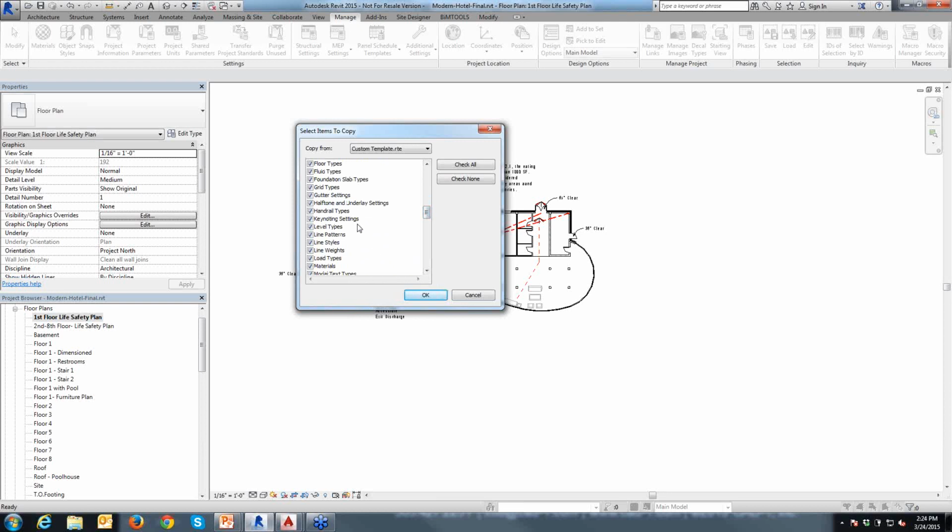System families, like Barbara was saying, floors, walls, those will transfer over, but not any of the standalone families or component families, or however you want to list it. Those are not in the list. But things like tags and stuff like that will be in there, view templates, filters, things that we've been talking about. Yeah, and this is also great, if you did build those wall types for another project especially, rather than going through all that again, just bring them over using your transfer project standards.